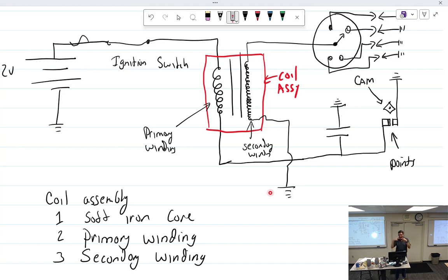And so the bigger the gap, the more voltage it's going to build up. So that's why it wouldn't do you any good to have a coil assembly that can make 40,000 volts if it only takes 20 to jump the gap. It'll never get to 40. It'll always jump at 20, and then you'll be done. Then it dissipates and goes back to ground.